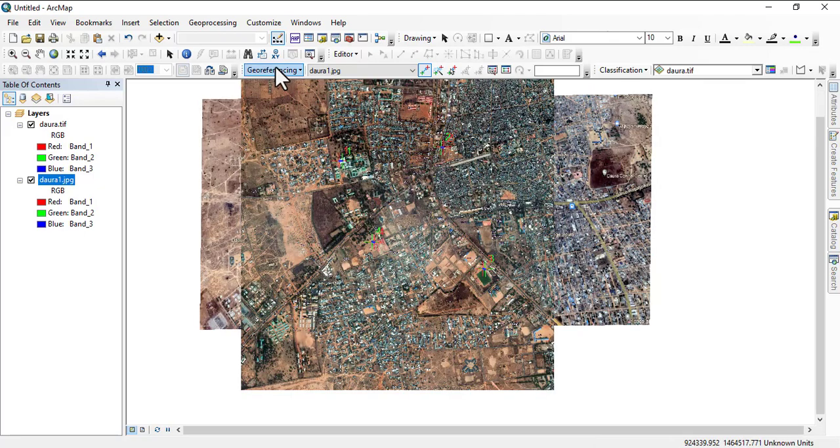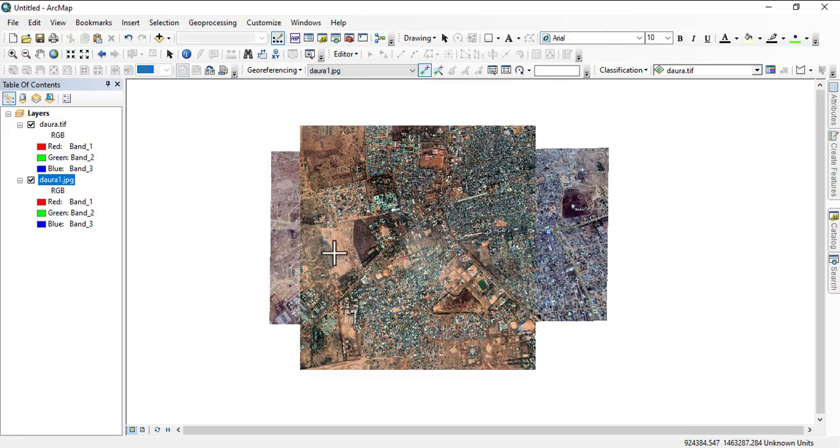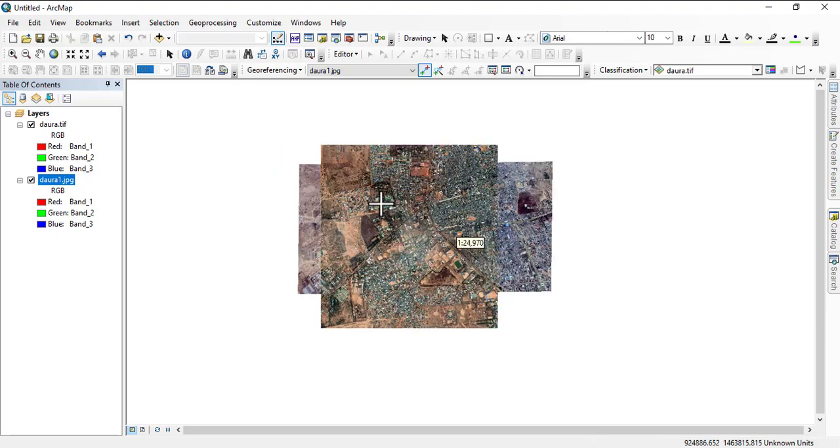And then once we've done that, we'll just click on update georeferencing and we're done. Now this has georeferenced the image, but we can see the discrepancies in the residual. So I will see you in the next video where we'll talk more on comparing these 3 methods of georeferencing, and then we'll wrap up this video.